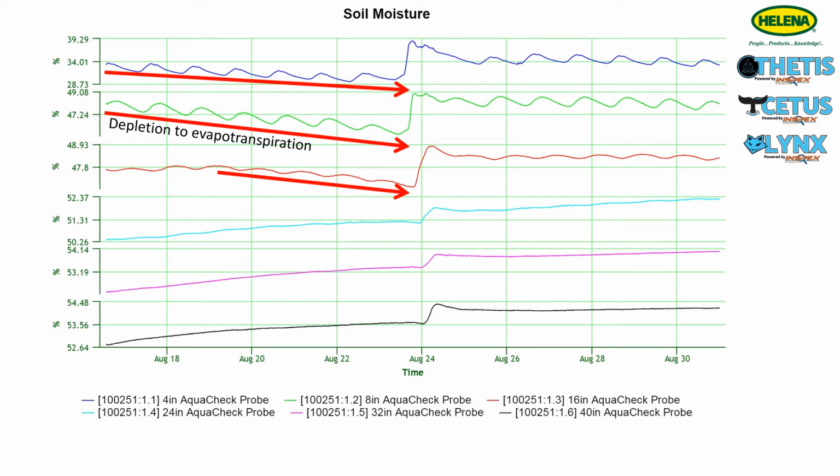The steeper the drop, the more the depletion of soil moisture. Soil moisture at the surface initially will have a very rapid decline as evaporation is quite active, followed by a slower decline as the evaporative processes slow down. Transient flow or redistribution of soil moisture may occur depending on the gradient as moisture moves from areas of wet to areas of dry.